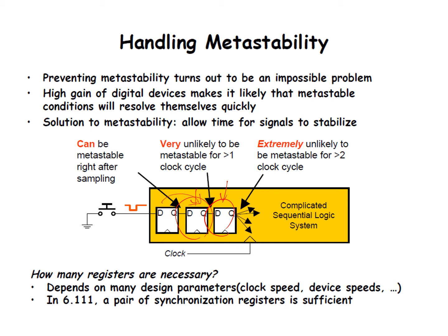So by the time we get to the last flip-flop, the output will be generated in a predetermined time, right? Even with this first one being metastable, by the time the next clock edge comes in for the second flip-flop, the first flip-flop will have resolved its output to either 1 or 0, right? So this is the standard way of avoiding such metastable issues.